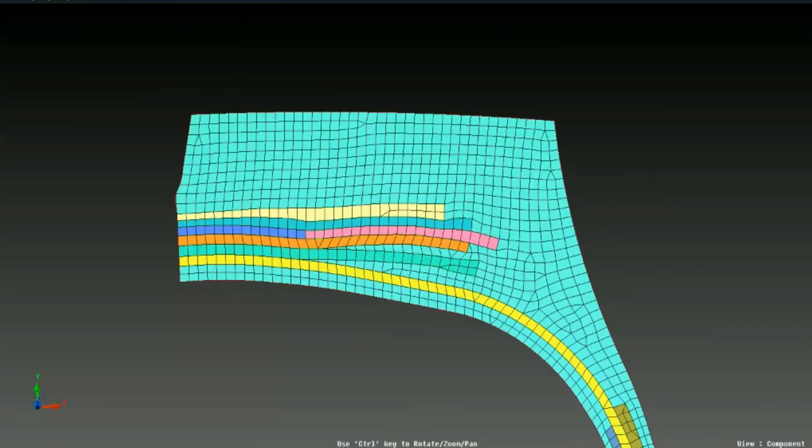Then we have remove tria. Whenever we have an opposite tria, or when you have a tria which you have to remove from your mesh, which has an edge nearby to it, simply click on the tria, middle click, and just remove it. So MeshWorks will very nicely go ahead and remove the tria as if it was not there.